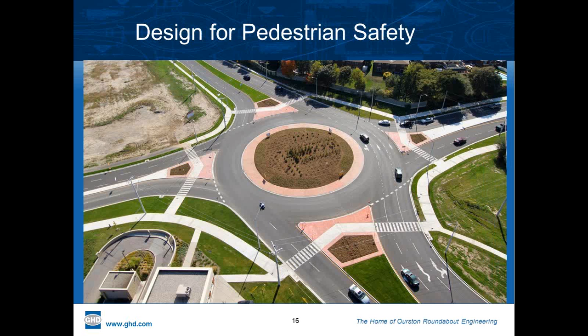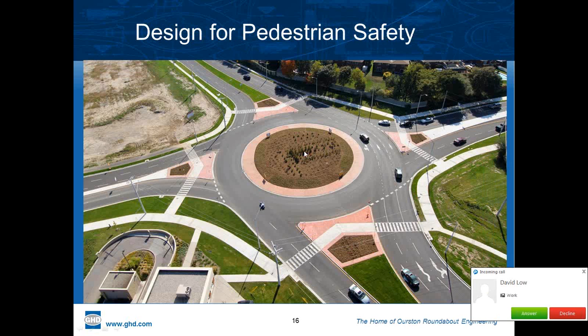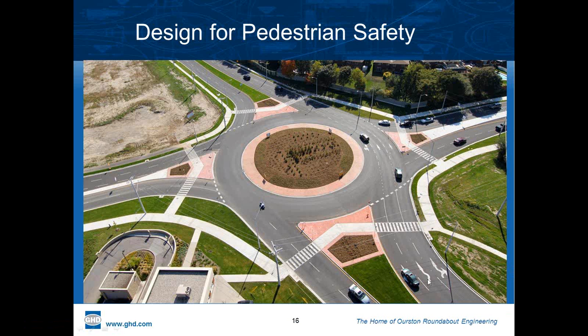So designing for pedestrian safety, we want to make sure entering vehicle speeds are low, and that's complicated and challenging to do in situations where you have 3-lane entries and it's difficult to get speed control. So pedestrian safety in the exit crosswalk is going to be a function of the speed of traffic in the crosswalk area. And if we can't slow the driver down on the entry, we're going to have problems with pedestrian comfort in the crosswalk areas downstream.